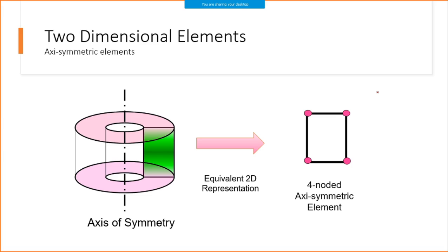So we'll now look at what is meant by axisymmetry. Just consider this is nothing but a cylinder, and you apply pressure on it. Pressure from inside, outside is atmosphere. When you are doing an analysis, you would divide this into 3D elements. In that case, it takes too many elements, too many nodes, and per node maybe six DOF. So obviously six equations, and it needs too much computation.